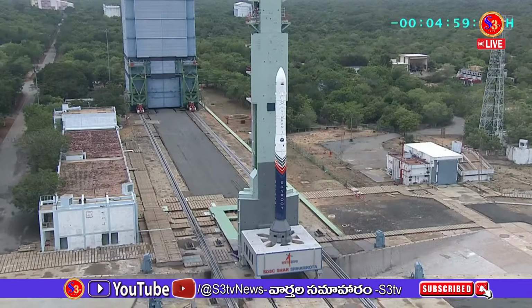It's around 0.1 watt per centimeter square. When Vikram-1 ascends into the Earth's atmosphere, its nose tip can face around 15 watt per centimeter square of heat flux. That's pretty large, I mean, as compared to humans on Earth. That's right. And we really need to design a thermal protection system to keep the structural design under the set constraints. If we don't design any thermal protection system, the vehicle surface might end up going to 1500 degrees Celsius.